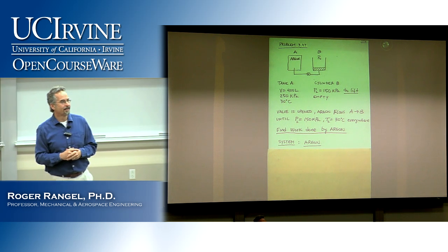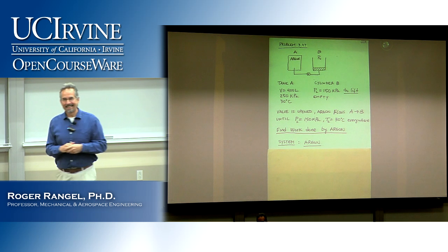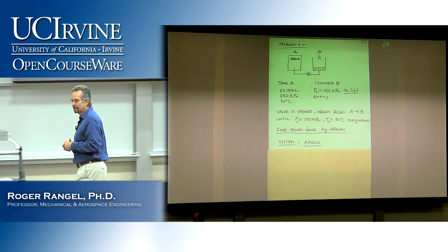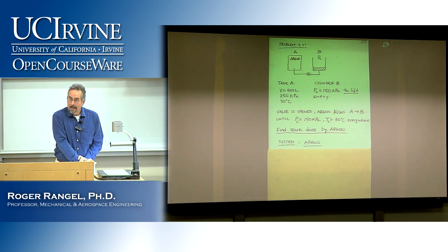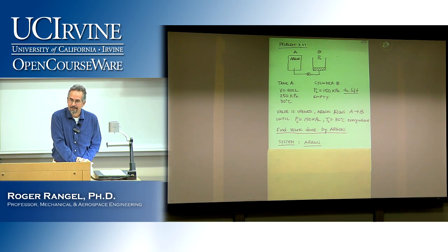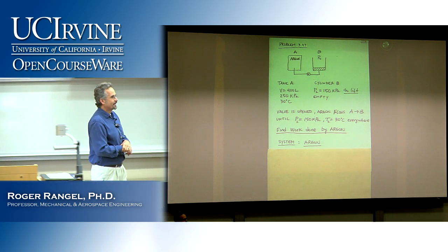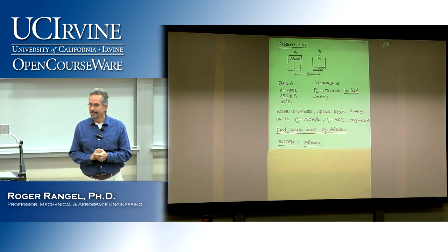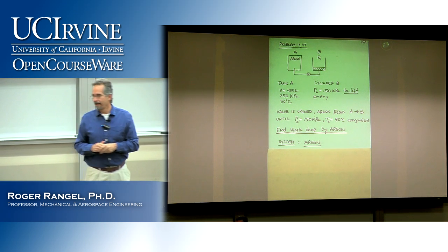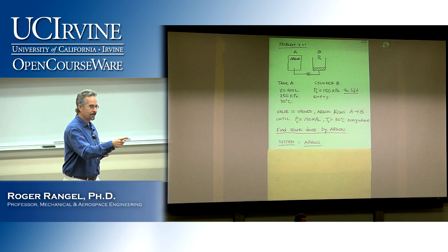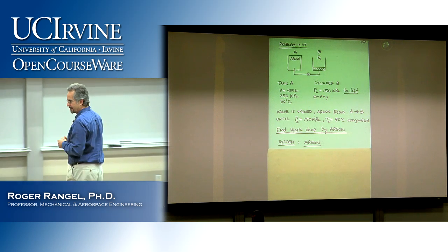That's in the back. Draw a force diagram. You could do that, but we already did that. Find the mass of the argon, how? Using PV equals MRT. Can I use PV equals MRT? You just have to use a different R constant. Well, we will use the R for argon that we can get in the back of the book. Yes, because you're at about room temperature and a realistic pressure.